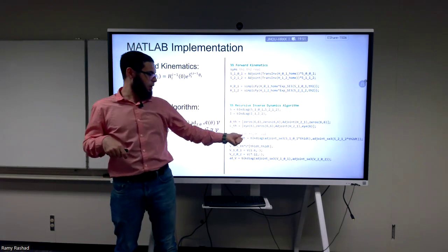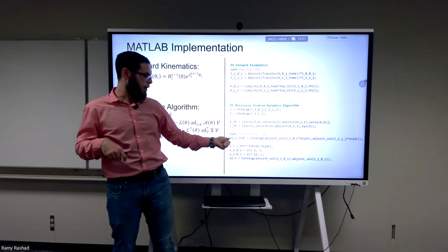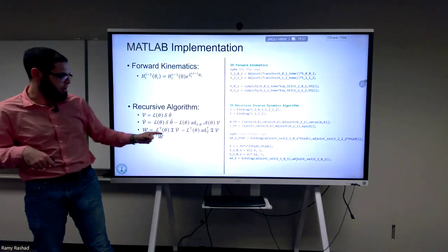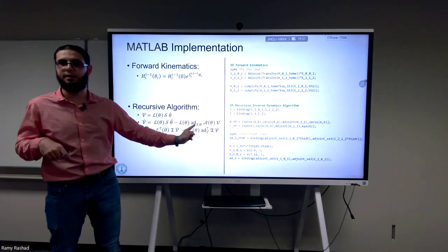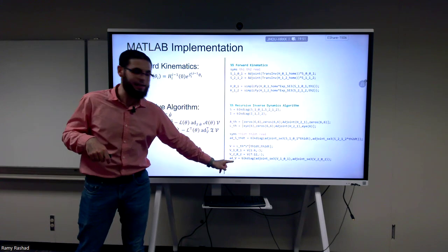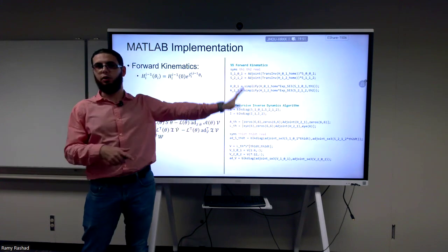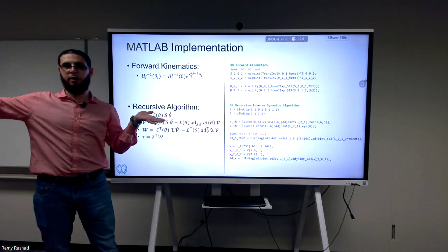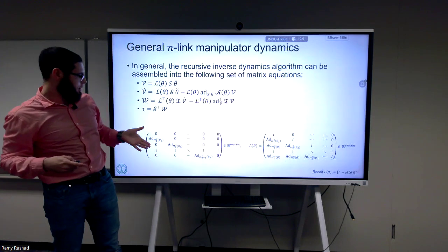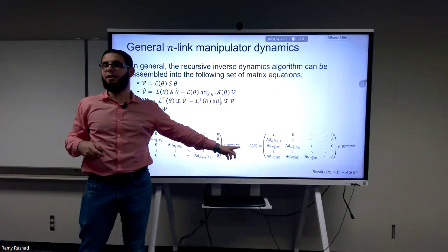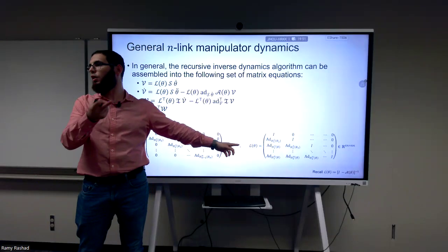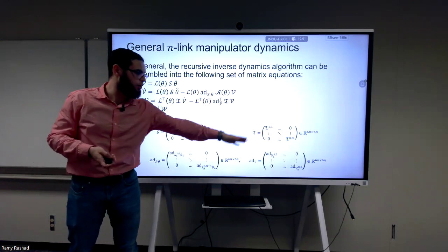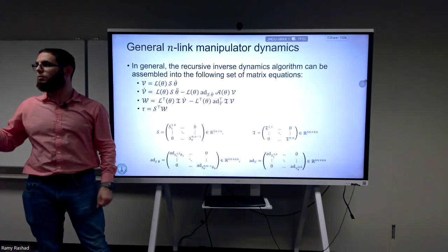Here I define theta 1 dot and theta 2 dot. And then I define the matrices, the ad of S theta dot, which is this one and that one. So I define these two here. All of these are huge matrices. You're going to have this code. You can look at it for yourself, and you see these are huge matrices. If you remember, go back a little bit. This one, for example, was 6n by 6n. So for this two-link manipulator it is 12 by 12. This is 12 by 2, 12 by 12, and so on. These are very big ones.